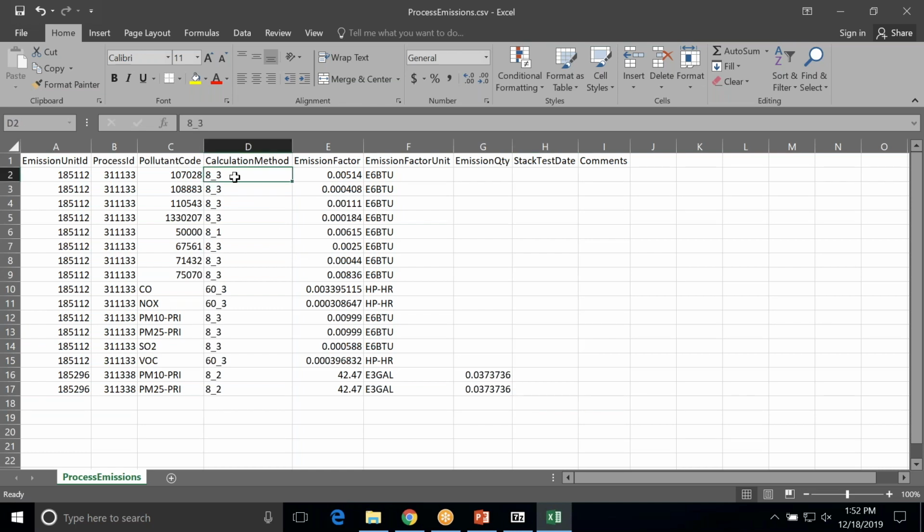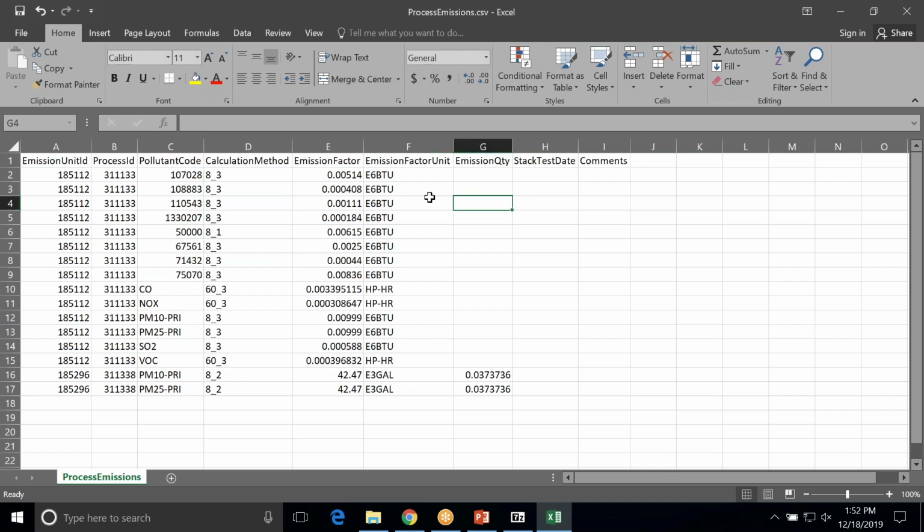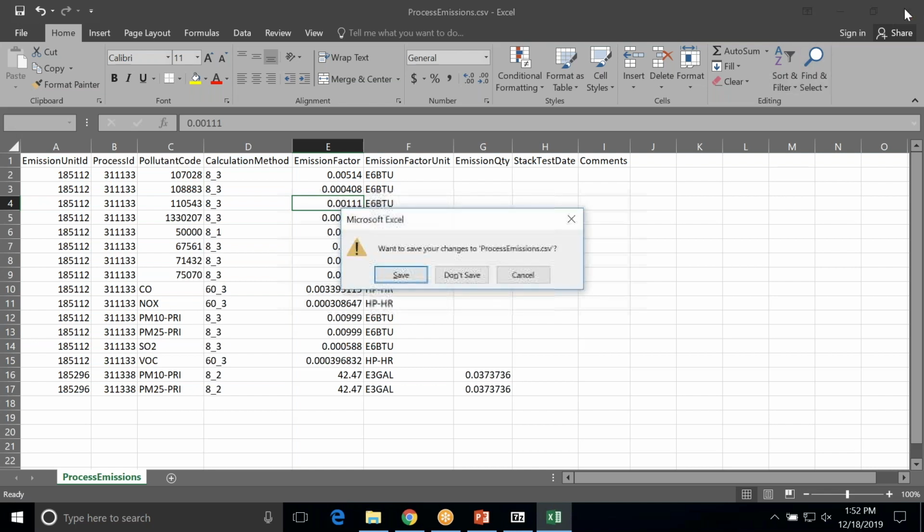Here, these codes are, I believe, if I recall properly, referencing AP42 values. Because of that, it knows what those emission factors are and will automatically calculate emissions based on that. So if I were to come over here and put in an emissions quantity, that value would get ignored. The application would then take the information I gave it about emission factor, method, value, and other information which I don't see here, such as control devices, sequences, and series of control devices, and calculate the emissions for me.